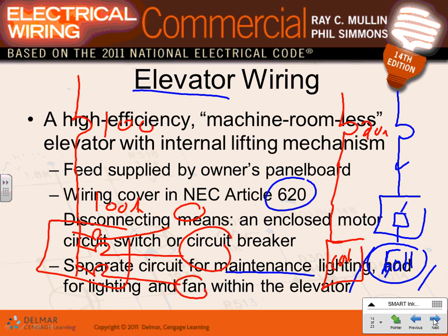Remember, disconnect fuse next to it, plus, of course, the overcurrent protection device, the branch circuit, and you need a circuit for the car that goes up and down. What's a common voltage for the motor that actually powers the elevator? I think this system is 208, three-phase. Typically, all of them, when you have an elevator, you're dealing with a 208 or 480 system, three-phase.